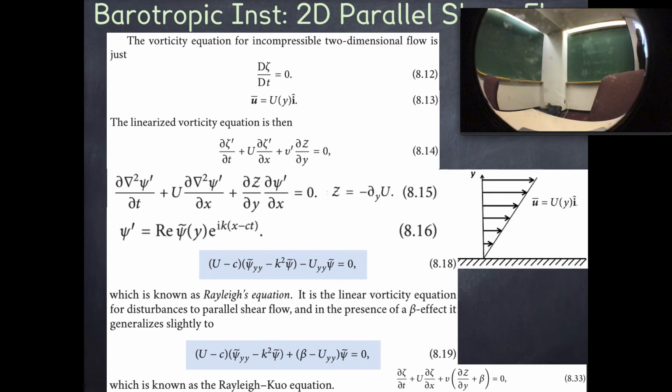That that's this? So here we go. Here's our PDE, still PDE, bringing in incompressibility. So we've got the stream function, the Laplacian of the stream function is the vorticity. Here's the stream function, where the v velocity is the stream function dx. We plug in an ansatz. Ansatz is the German word for guess. We guess and check with this form. Plug it in there, and we get this equation.